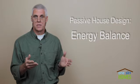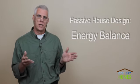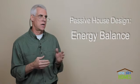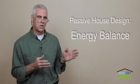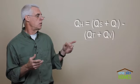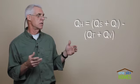through different climates. So there is an equation, a superbly elegant equation, thanks to Dr. Feist and his colleagues at the Passive House Institute, and that is as follows. QH equals QS plus QI minus QT plus QV. Or said more simply, heat flow is passive gains minus passive losses.